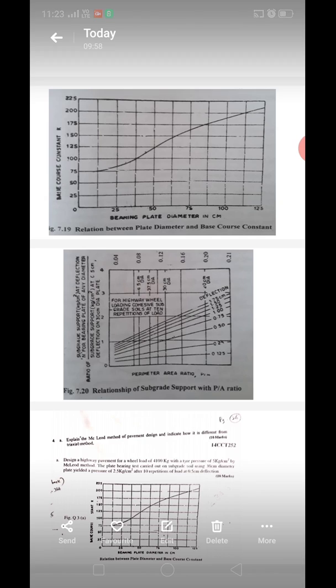And for a highway wheel loading for 10 repetitions, the values are given, and for various dia plates in between lines we see 45 centimeter, 37.5 centimeter, 30 centimeter and 20 centimeter dia plates, and inclined lines are nothing but the deflection for various deflections from 0.125, 0.25, 0.5 like that up to 1.7 centimeters.